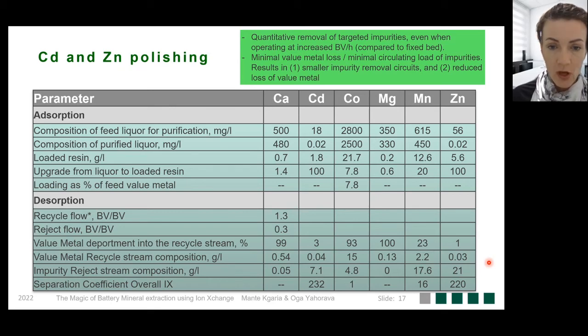impurity removal system. So in comparison with fixed bed application, or for example carousel application of ion exchange, moving bed technology allowed to decrease resin inventory significantly, and also provide impurity bearing streams of a composition which would be much easier to manage in comparison, from the point of view of the flow and of the grade downstream.